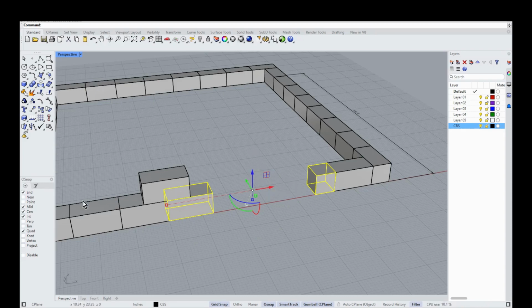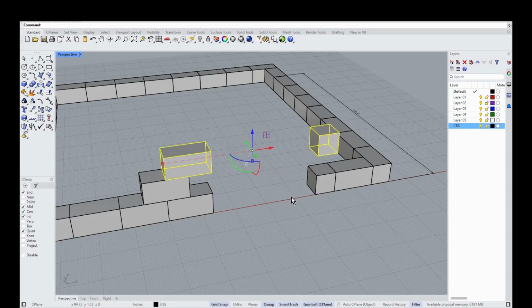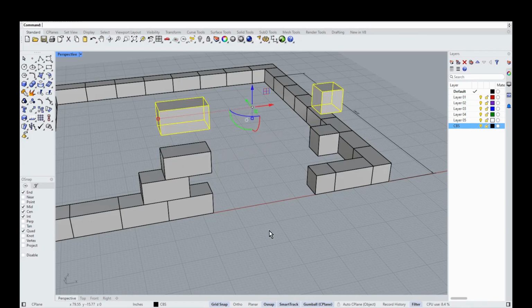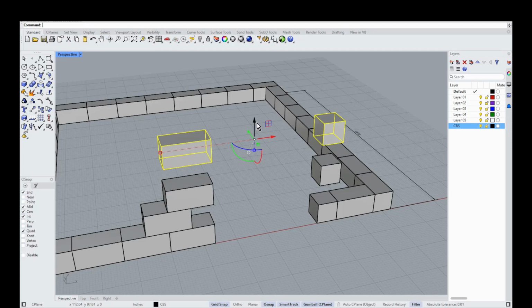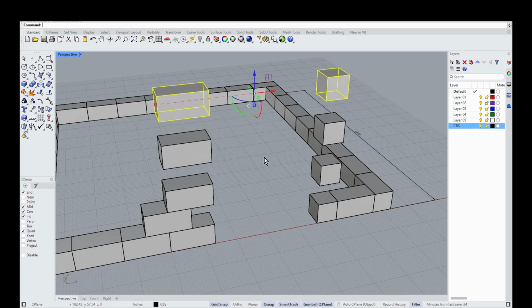Of course, block courses going vertical, they're going to alternate, making the classic brick pattern. So go click on it with an alternate, and we're going to go 16. So that's going to take it to 16. I'll just do another 16, and the old number is still in there. So all you have to do is click on it, and you physically have to change it to something else. So go up like so,